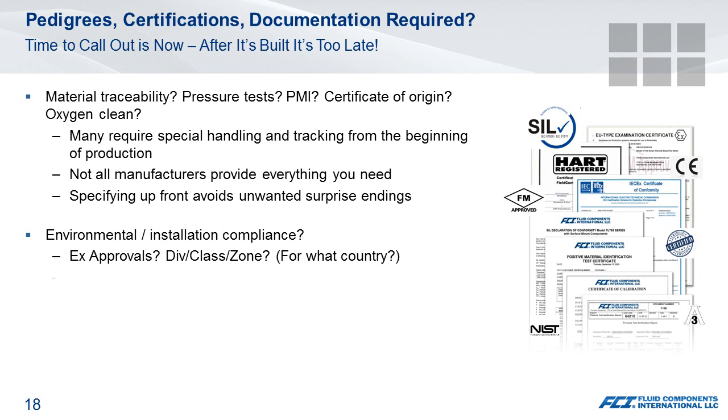And the other thing I would tell you is that not all certifications are alike. Explosion-proof ratings, for example. Some manufacturers are just doing a buyout enclosure. Is a rating just on the enclosure adequate, or is it a full instrument certification that you're looking for? Outputs, digital bus comms, some of the bus comm organizations have their own testing facilities and will validate the product against their standards.